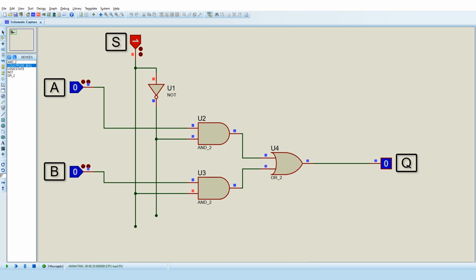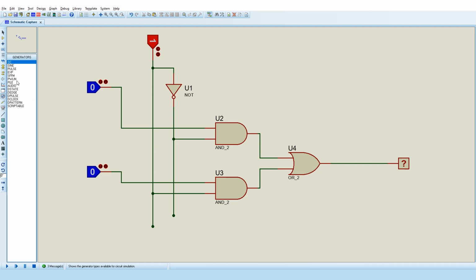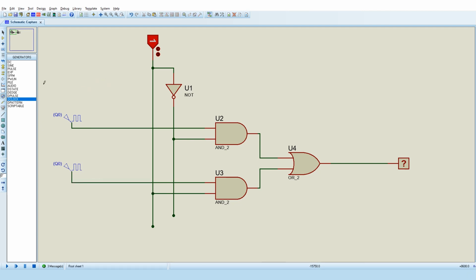So it works well. I'm going to go into generator mode and get some digital clocks to simulate the data on channel A and channel B. There's channel A's data, there's channel B's data. Get rid of the logic states because the logic will be whatever the clock is at the time. And I'll automate the channel select as well with a slower clock signal. Get rid of that logic state because the clock will drive the selection and the data. Get some logic probes to look at what the selector signal is and the data from the clocks on channel A and channel B.